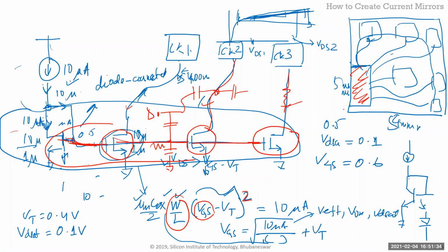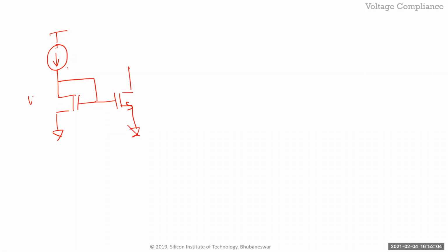All right. Okay, voltage compliance, and that's something I've already talked about. So now the current mirror looks like this. You take a current source, and that can be another current mirror, obviously, but somewhere it has to be one source without a current mirror. And let's say we have that. So we put that into a diode connected transistor, and if this W by L and this W by L are the same, and this VDS is greater than VDsat, and lambda is really, really small, let's say this is IB, then you'll get IB here.